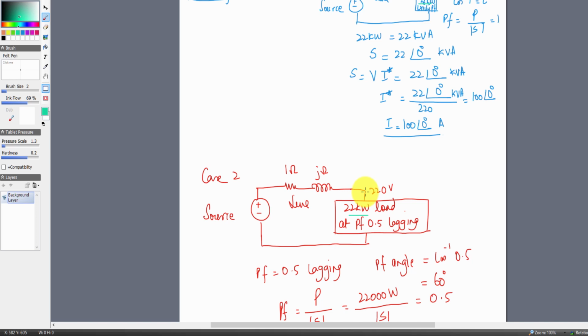So if the power factor is, let's say, less than 0.85, I think, you have to check the KE tariff, the Karachi Electric tariff. If it's less than a certain value, let's say less than 0.85, they are going to charge you more per kilowatt hour. They could have reactive power meters as well, or a power factor meter as well.